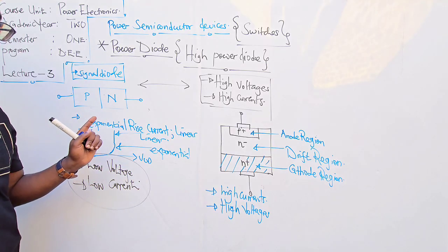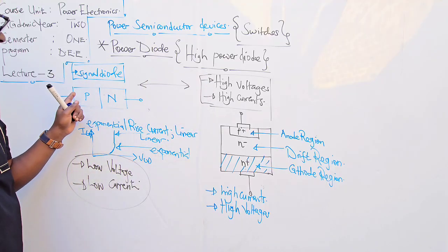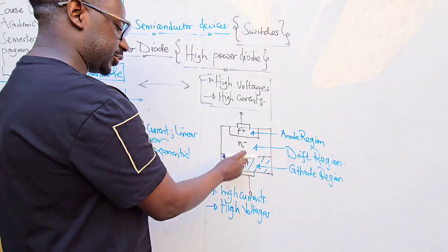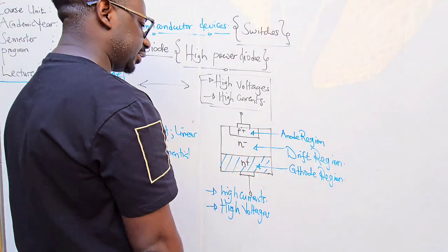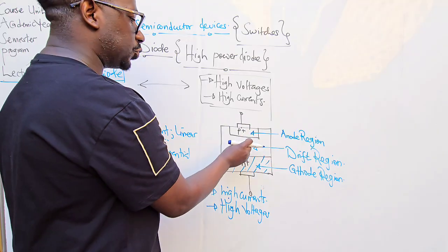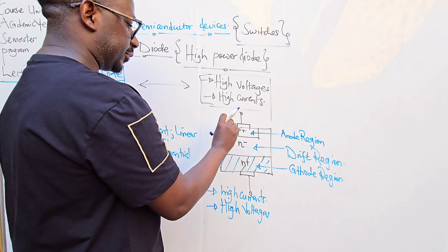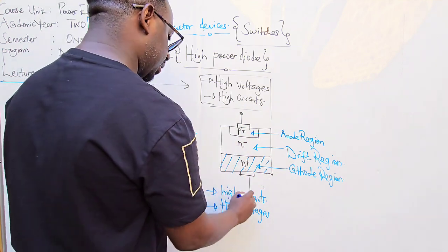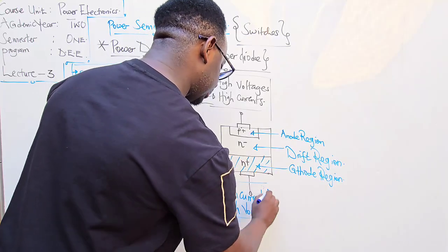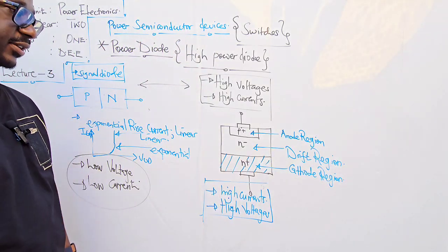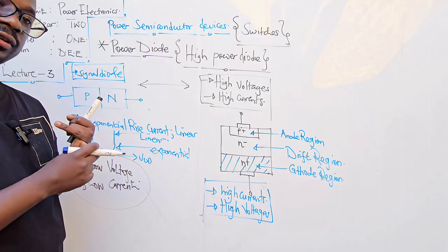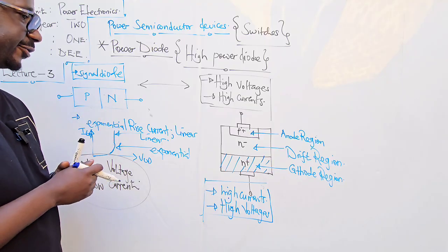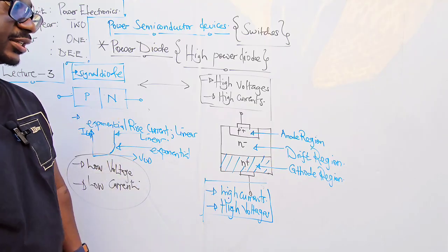We're going to see a minor difference with the IV characteristics of a power diode as opposed to the signal diode. That construction alone allows high currents in that direction and ensures that there is a small resistance to the current in the forward conduction mode. So that's how we end up with a high current, high voltage conducting device. Still, it will block current flow in reverse bias. It will have the same conduction modes as the signal diode, but with a few minor changes.